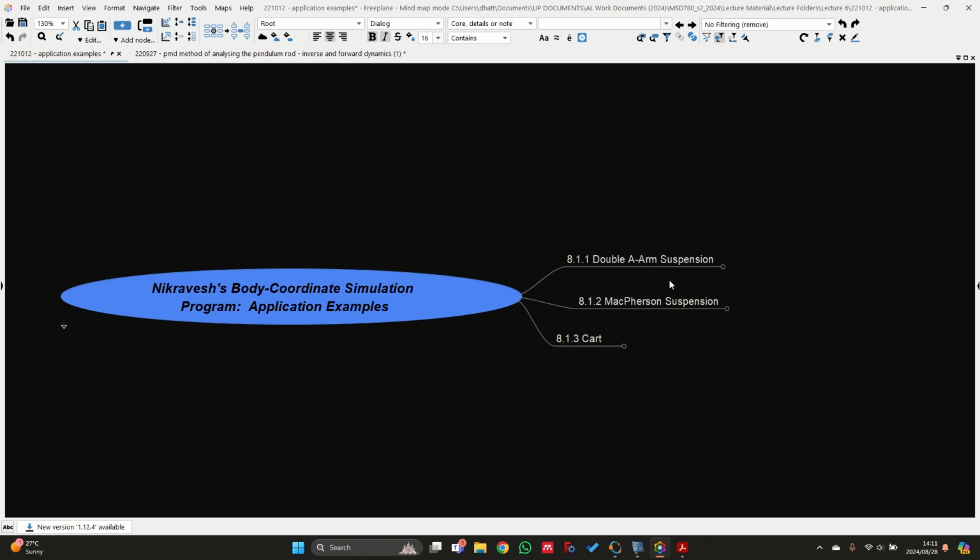So today we're going to look at the car that is rolling on a flat surface. We're going to look at some disc joints and how those are going to affect the overall dynamics of the system, and also delve into some of the Jacobian matrix, the details with regards to how we can set up our own Jacobian matrix.